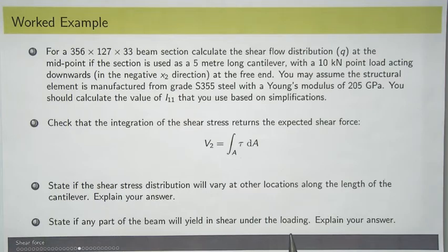So generally the reason that we're checking for shear is obviously to see whether it presents an additional way in which the material, so the steel that the beam's made of, might actually fail. And so it's just something that we should do. You can also find that shear increases the deflection, but that's a little bit beyond the scope of what we're going to look at here.